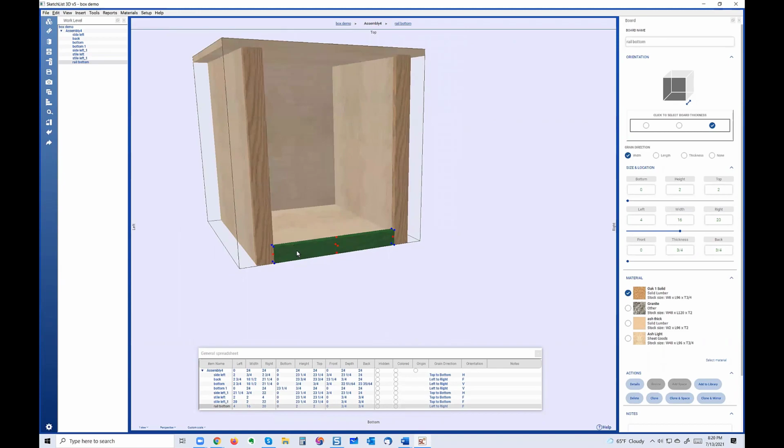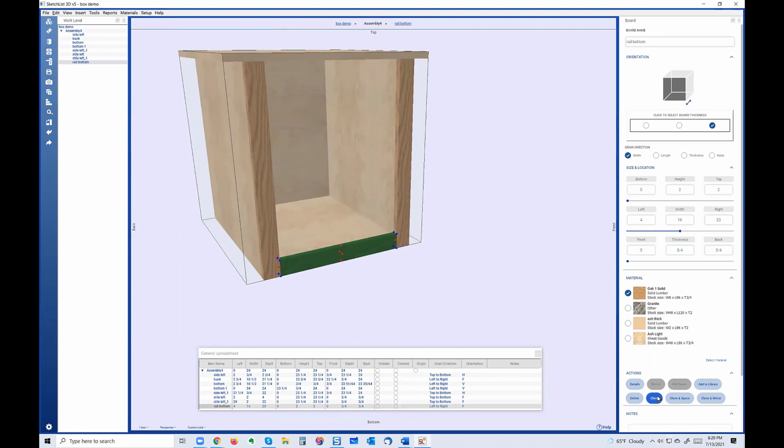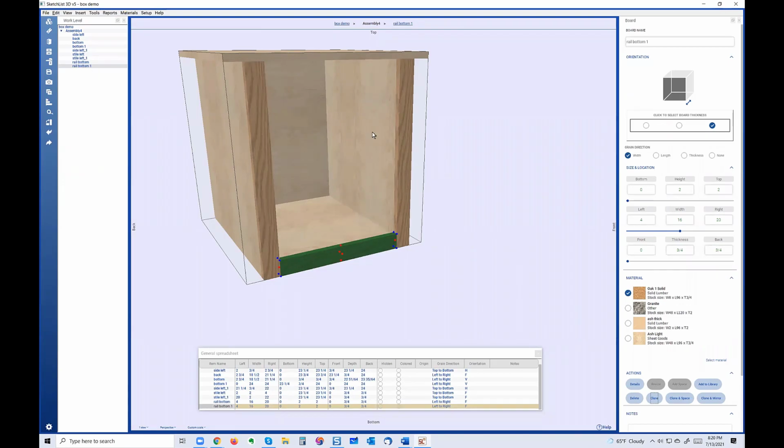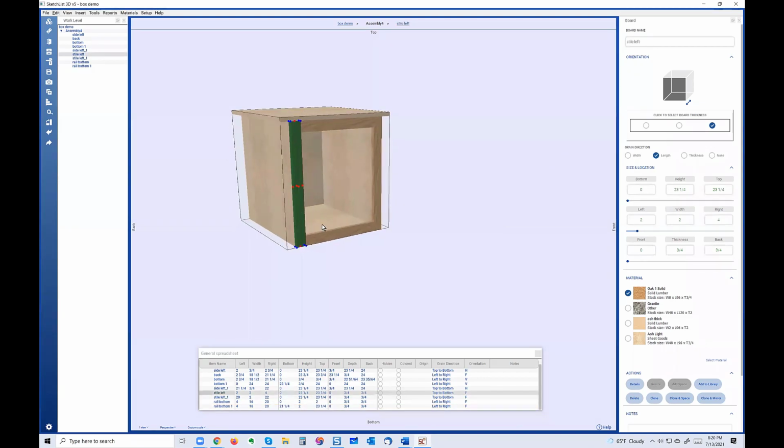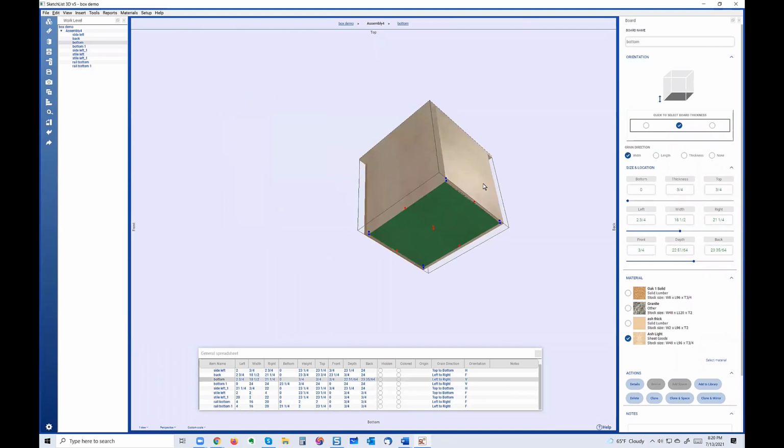Now, if I take this and I clone it, I know when you're working in a project, you start just knowing things about where things are located and their sizes. So I've worked so much with this top value, I know it's 23 1/4. So I want this cloned rail to have a top value of 23 1/4. Keep the height the same, click on that bottom button, and there it is. All right. And we're in good shape.